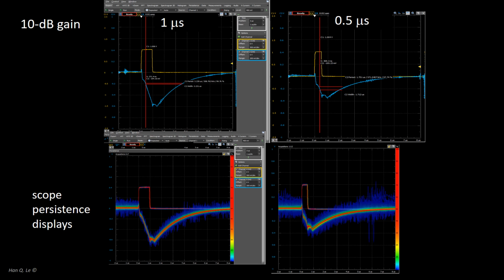If a system is linear, it can be represented as the difference between two time-delayed step functions, as in step A6 above. The steady-state responses of the two time-delayed step functions would cancel each other, hence, the impulse response can be viewed as another measurement of the rising edge behavior of the step responses. The part of interest is the tail of the response, which represents the speed of the response, and is to be studied as a function of the gain.